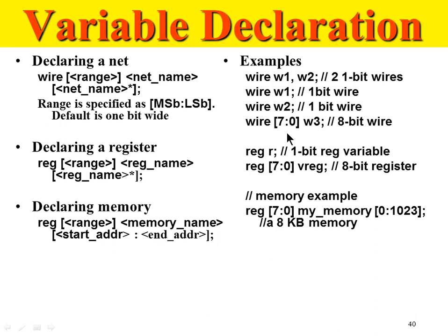That's microprocessor architecture language: little endian and big endian. This is a little endian system. Endian is spelled ENDIAN. This is a little endian system, 7 down to 0. I declare a multi-bit wire using this format. I declare a multi-bit register using this format.